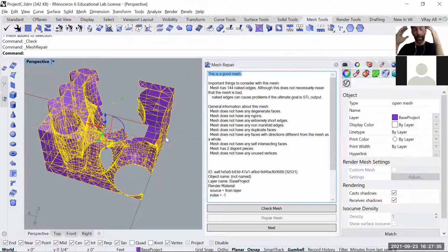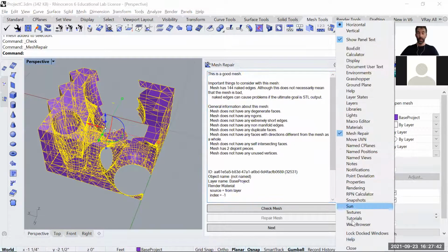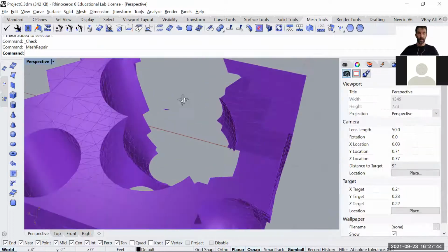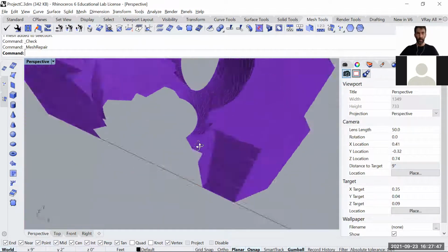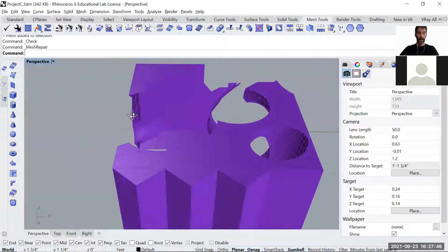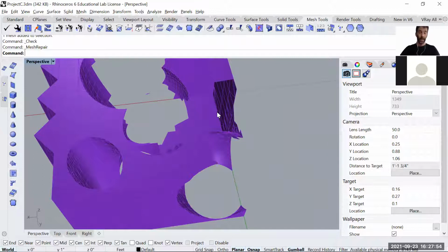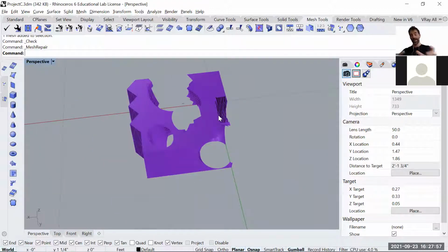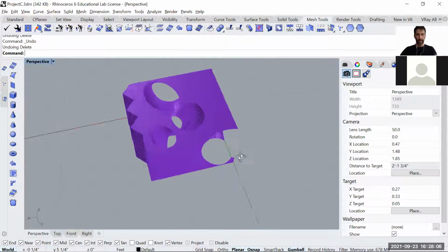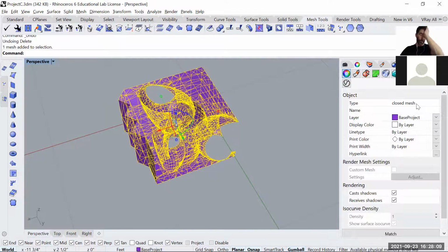So I guess there are two things. One is good practice. The other one is trusting Rhino into doing things. Obviously, the one that we're dealing with is not a good mesh because it's all open here. It's not watertight. My guess is that Rhino would be able to fix this, but not in a way that the 3D printer will return the model to us as we intended. So be careful with trusting. The first check of all is always to make sure there's a closed mesh.